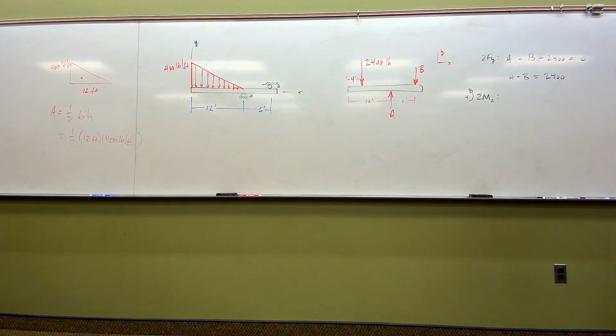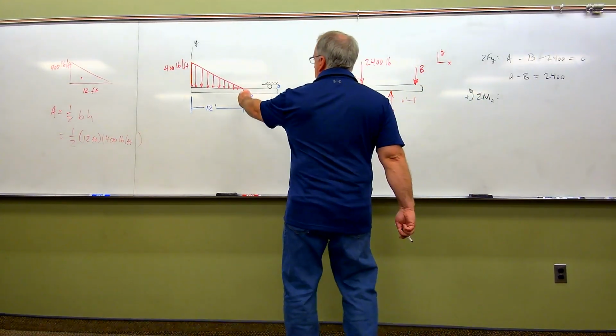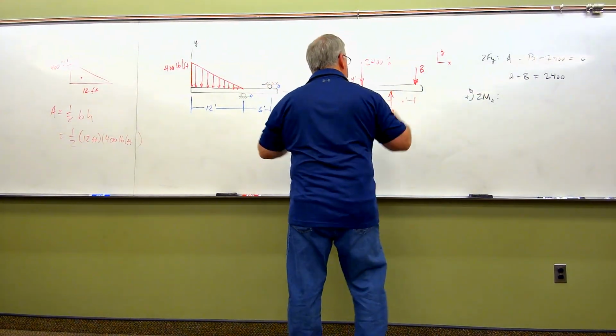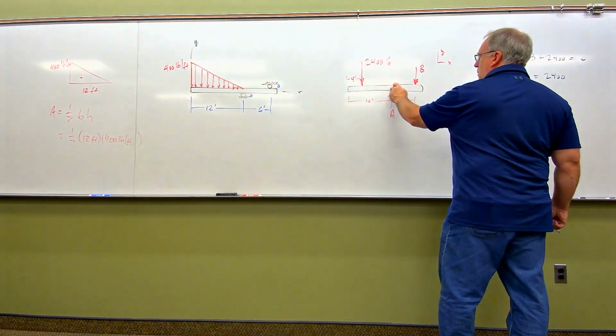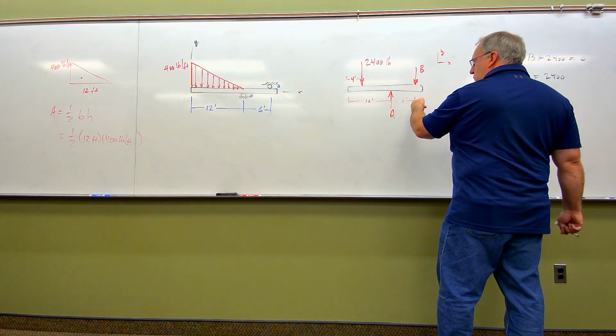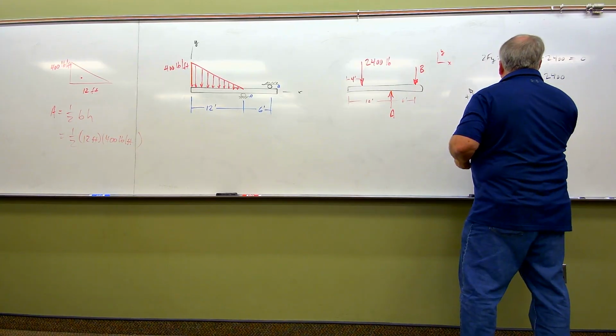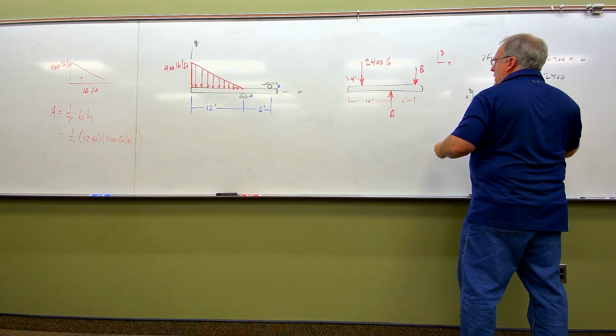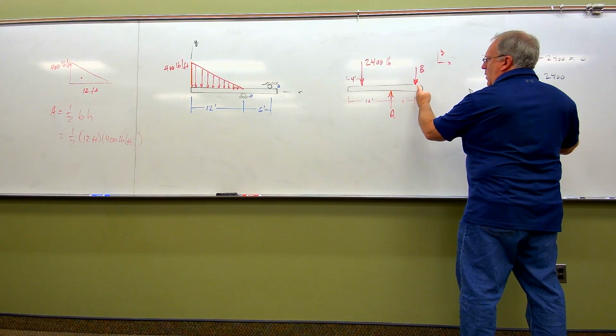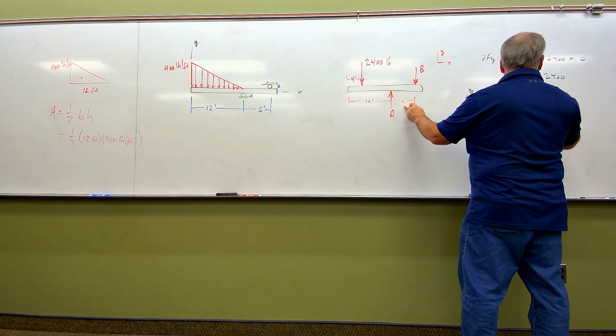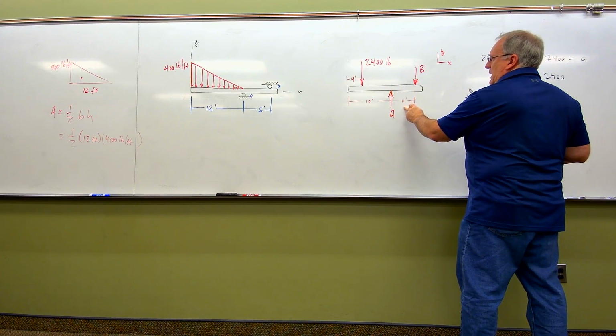So now, from point A, over to the line of action of force B. So we look at B here. We know that our moment center is here at A. So B with respect to the moment center is doing a clockwise rotation, therefore it's negative. So minus B times the moment arm from A over to the line of action of B, which is 6. Takes care of that one.